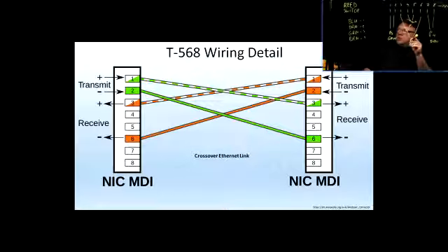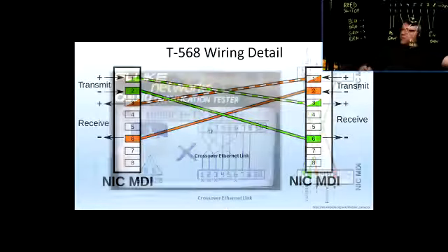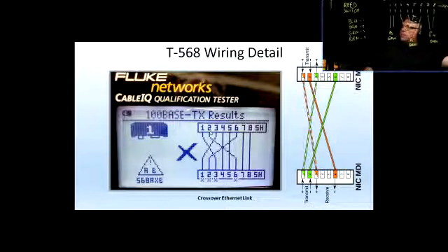And sometimes you're going to see more cables. You're going to see the blues and browns also crossed with each other. Well, the reason for that is, can we see that? Yeah, so on the tester, this would be pins 1, 2, 3, 4, 5, 6, 7, 8, and shield is not connected because that's in case we had the shielded twisted pair.